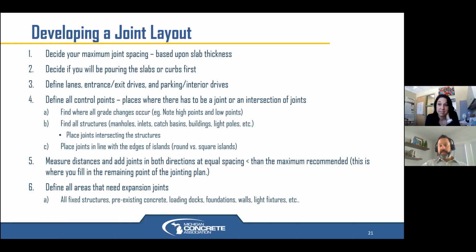I have not heard of that big of an issue. Yeah, there's 2 things. Either your structures are in place and you're pouring up against them, near them, up to them, and then you have to make sure your saw cuts get in on time, because that structure now is your weakened plane. That's a stress concentration area, if you engineers understand that from your schooling in the past. And so you need to have joints that form cracks, because they will occur, intersect that structure.